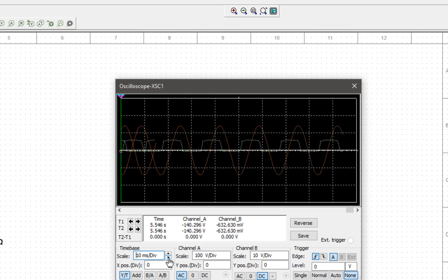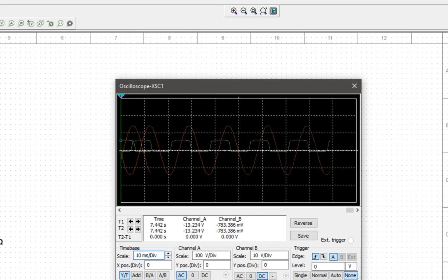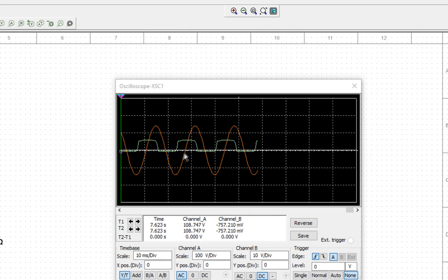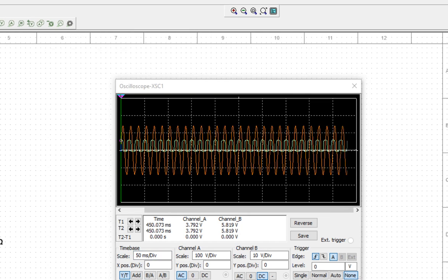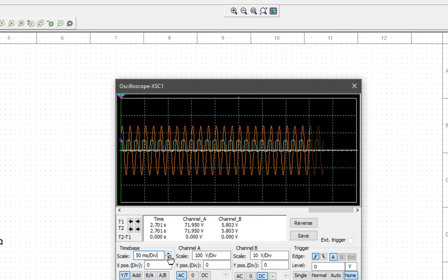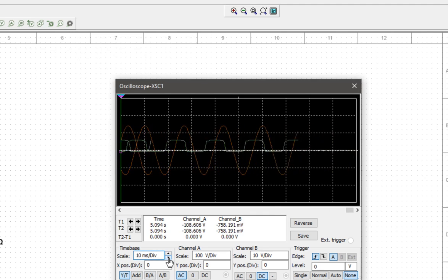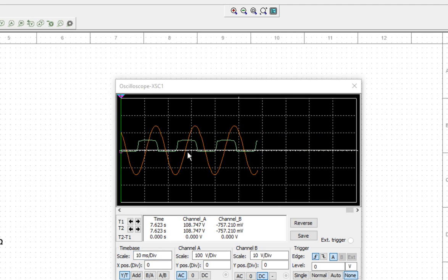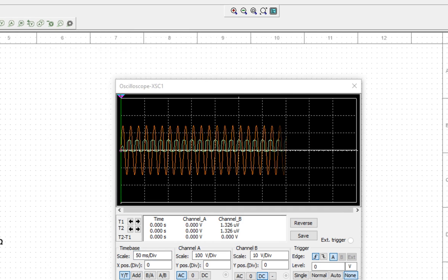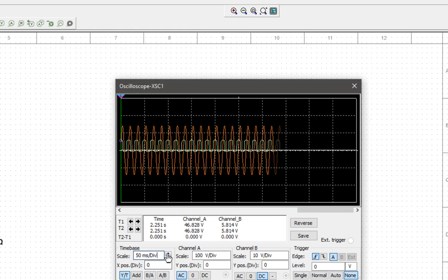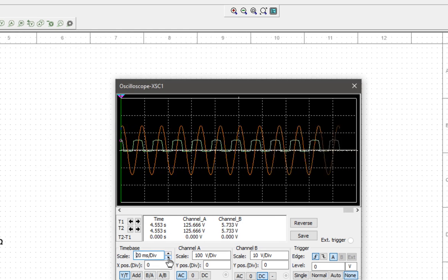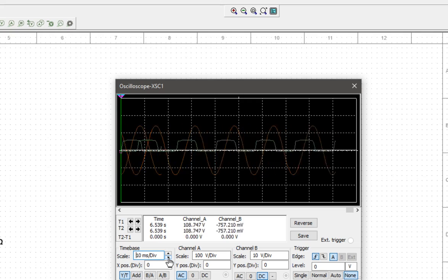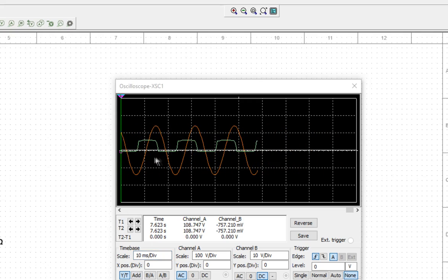The test demonstrated that the circuit without the transformer gives an average voltage of 5 volts, but the analysis of the wave with a virtual oscilloscope demonstrates a kind of square wave working at almost 50 Hz.